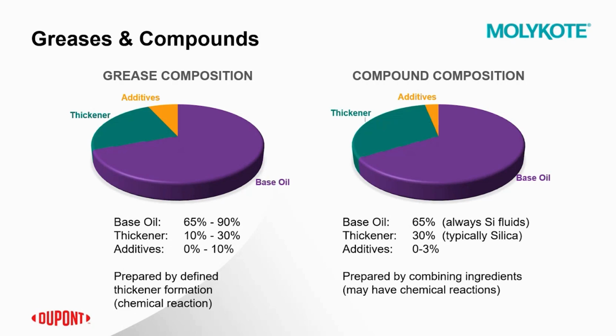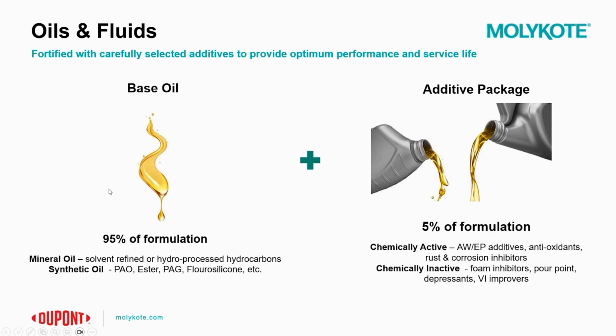So when you combine those three additives together, you could minimize the effect of the friction modifier, sometimes overall mitigate the effect of the corrosion inhibitors. So it's really important to consider the combination of additives that you're adding to the formulation. And overall, the proper balance of additives is very critical for minimizing the harmful effects of the antagonism with the additives. So lastly, we could take a look at our fluids and oils.